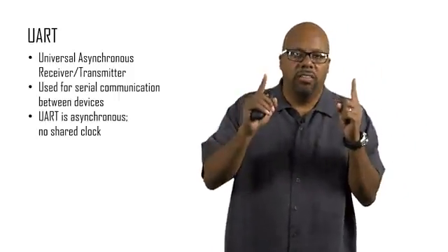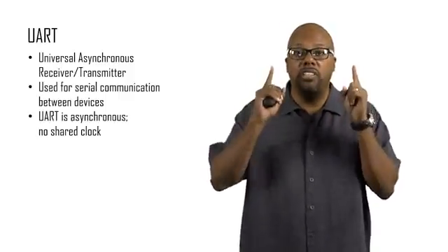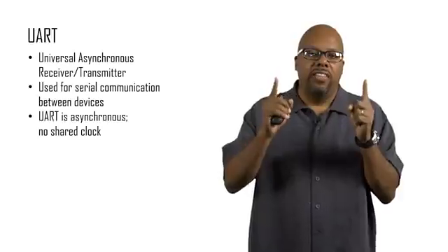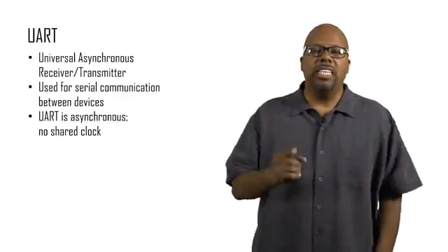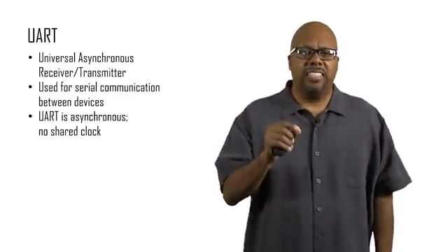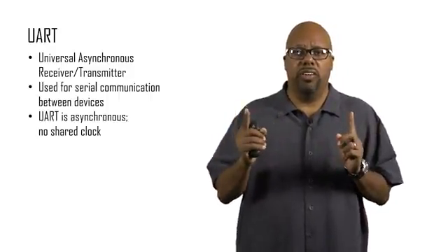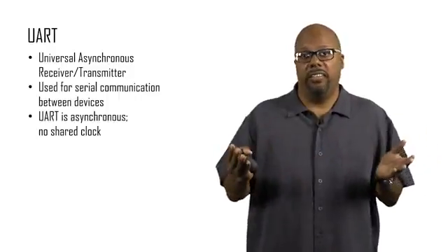So how far does light travel, even light, which is the fastest, in a nanosecond? I don't remember the distance. I'd have to compute it, but you can check into that. It's some short distance, okay? This isn't a lot of distance, and a motherboard can be bigger than this. So what this is saying is that in a clock period, even the fastest signal can't travel from one end of the board to the other. And remember that our electrical signals are traveling a lot slower than light is.